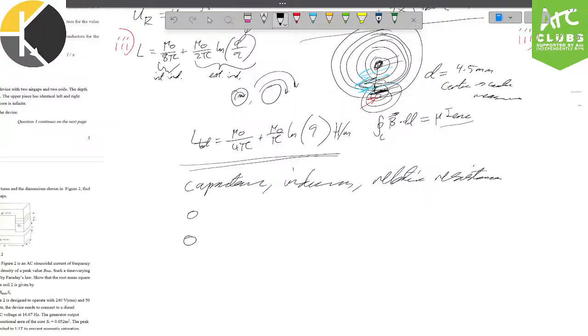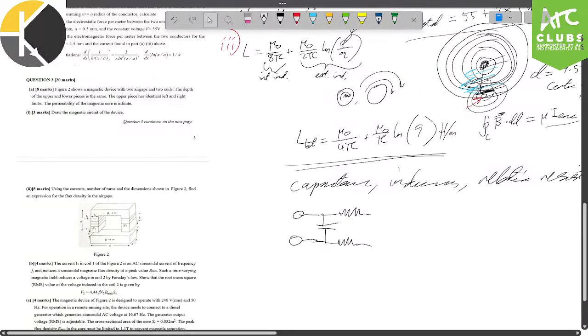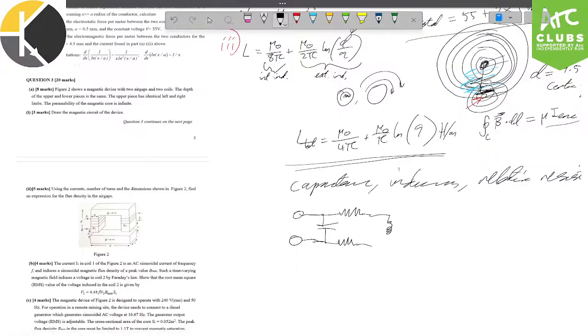Just looking into the circuit, first thing I'm always going to see is typically a capacitance. This is just the binding of the top and bottom transmission line channels. We have the resistances given by the conductivity of those transmission channels. We could try and potentially break this down portion by portion as we would in high frequency. However, for the sake of this question, they really just want to see what goes where. Something the answers for this document do, which I'm not the most sure on, is chuck the inductor in parallel with the load.